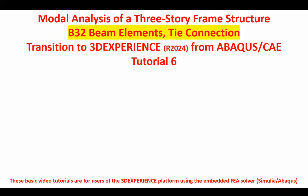This is tutorial number 6 in the playlist that I'm preparing for modal analysis of shear frame structures. In this particular problem, I will be using beam elements to model the frame, and I will create a tie connection between nodes that have different node numbers but are physically at the same location, in order to make sure that everything moves in unison.